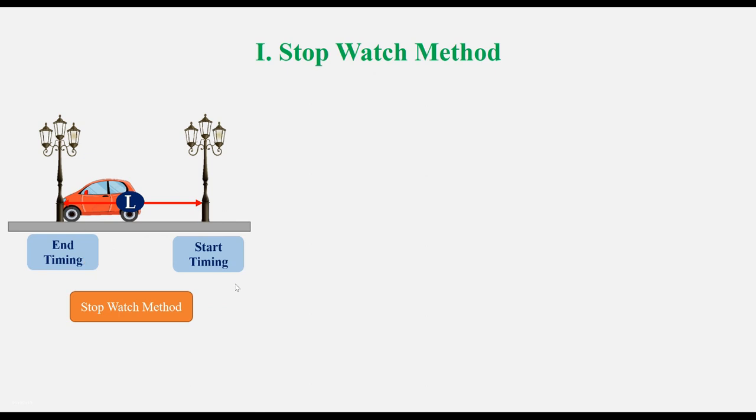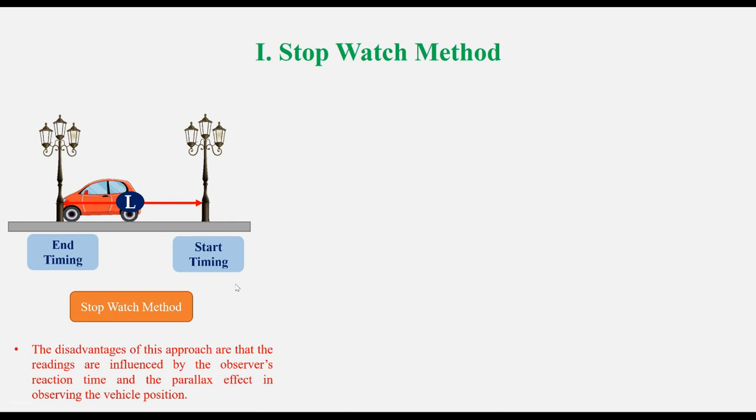Now the problem with this method, or you can say the disadvantage of this method, is that the readings are influenced by the observer's reaction time, and the parallax will affect the observation of the vehicle position. The accuracy of the stopwatch is also important because the length is small, so the measured time is also small, and a small error in measuring the time will multiply the error in the final speed value.